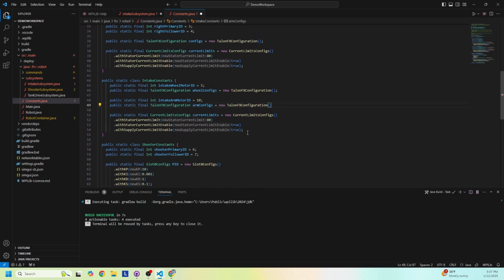Most importantly are its cruise velocity and acceleration, which, remember, for that trapezoidal move tells you how fast you can speed up to that speed that you're going to hold. Then cruise velocity is the speed that you're going to hold. And yet again, with that, acceleration is how fast you're going to slow down from that speed.